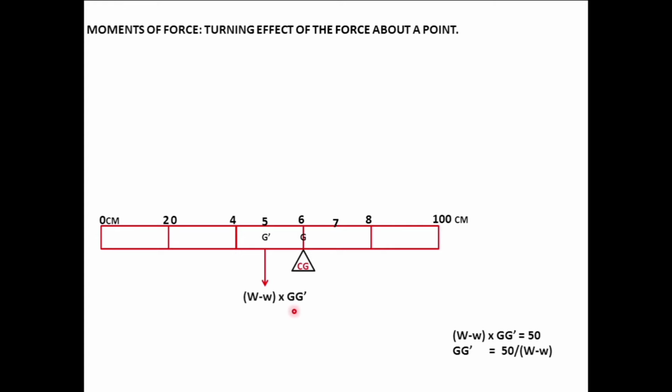So what is this final weight and the distance that the G is going to move so that I can balance the weight is going to come up something like this. W into 2. And the distance I've got to move would be the anti-clockwise moment that was created, divided by the new weight. And the distance that G has shifted here is 10 centimeters, what we just saw.